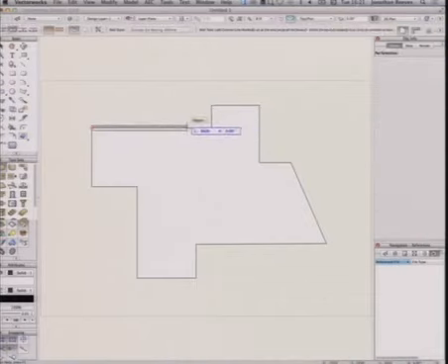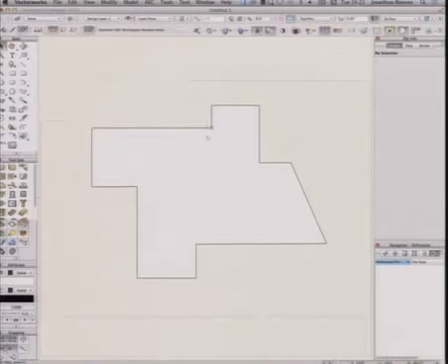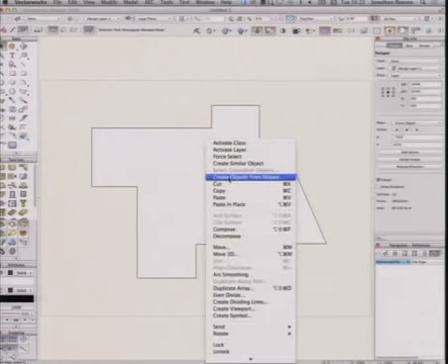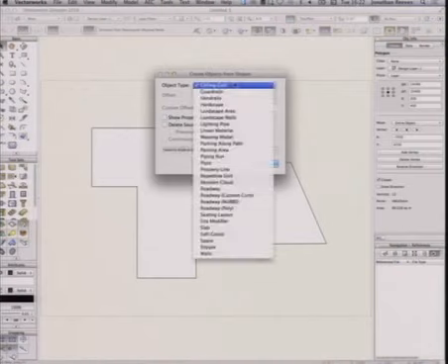Or I can hit the U key on the keyboard to cycle through those modes up on the top left. So I can trace around the inside, outside, or center line. Let's just go for it in a different way. I'm going to right-click, create objects from shapes. And I can turn that polygon into a number of things. So I can turn it into walls. Okay, so that's my first little step.